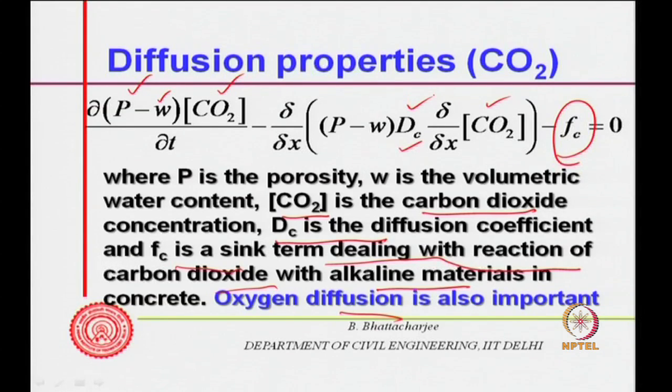Permeability can only give you qualitative information, a better concrete and poor concrete, but there is a lot of research to be done here in order that one can actually use them for practical purposes. The equations, the material properties, solving them may not be a big problem with the kind of numerical methods and computers that are available today, but it is not easy to find out the coefficients in the equation.